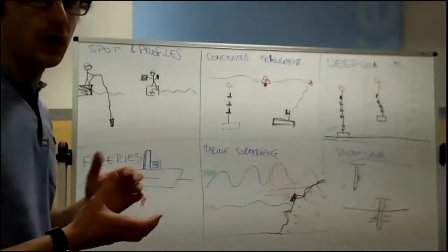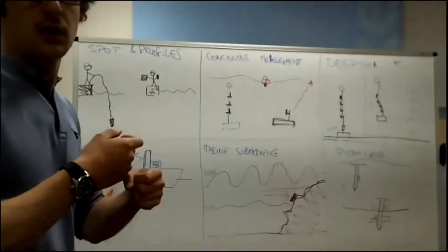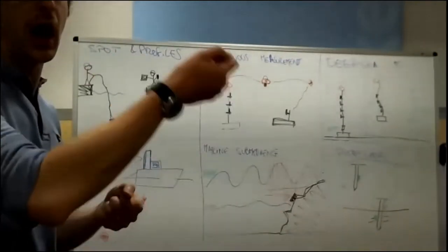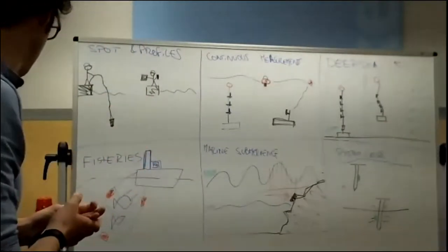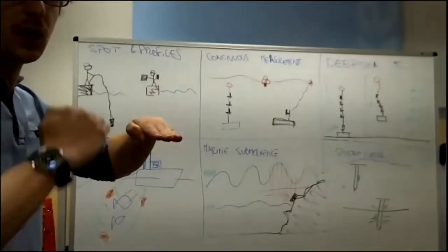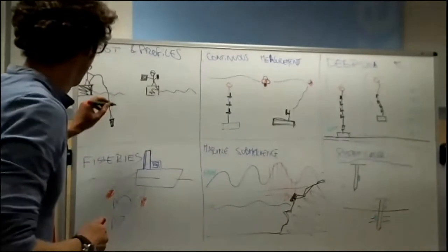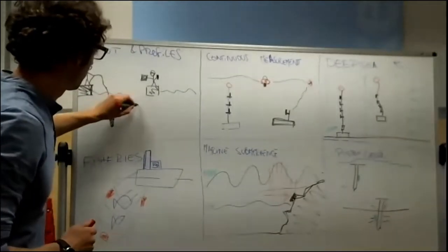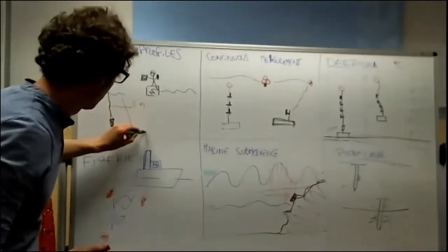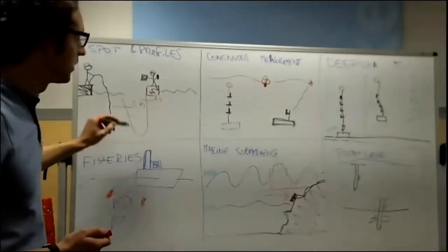The second one would be a pressure-based measurement. Say, once I am in the water, I want to start the measurement, and once I'm out of the water, I want to stop it. Typically, in that case, you would put a start condition a little bit below the stop condition. For example, I'm starting to measure when I am at 2 meters depth. I do my profile, I come back, and I stop the measurement when I'm at 1 meter depth.